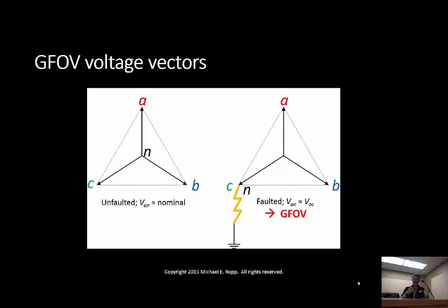But remember, I've now disconnected this circuit from the substation. So it's being fed by this ungrounded voltage source. The voltage source, because it is ungrounded, doesn't know where 0 is, right? All the voltages are relative to each other. So let's say this is a synchronous generator. It doesn't have a ground.